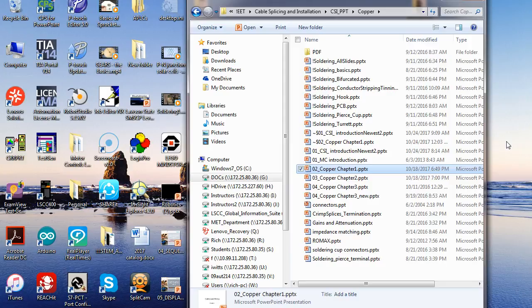Orange-white, orange, green-white, blue, blue-white, green, brown-white, brown. That's the B. The A, you swap the greens and oranges. All right, guys, y'all okay?